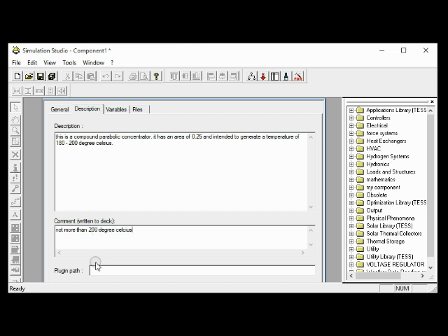And lastly, the plugin part, which contains a path to an external application which will be executed to modify component properties instead of the classical properties window. Such plugins can be developed by the user as described in the annex. For example, you may want to use Microsoft Word or MATLAB or a text notepad editor to modify some component properties of this model.